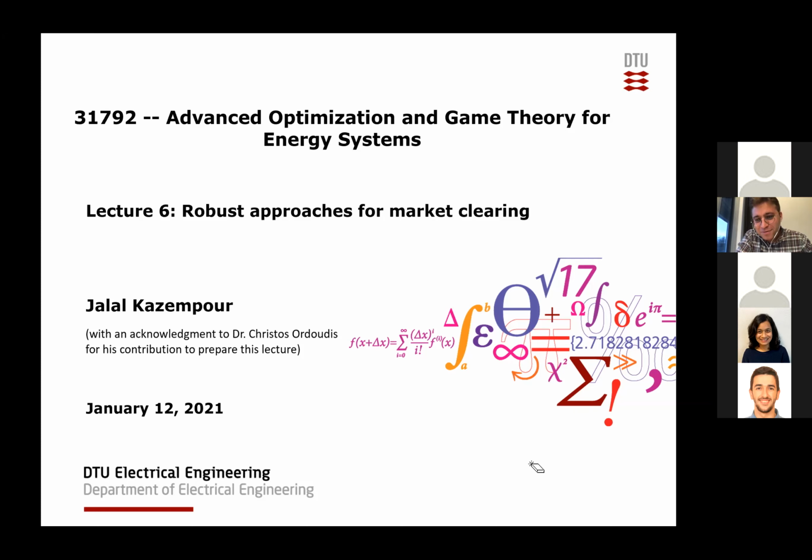Our only source of uncertainty in the previous example was wind power, whose production can be between 0 and 70. 70 is the installed capacity. So in stochastic programming, what we learned yesterday in the previous lecture, we defined 4 scenarios, 30, 40, 60, and 70, with the same probabilities, specifically in that example, and then we minimized the total expected operational cost.